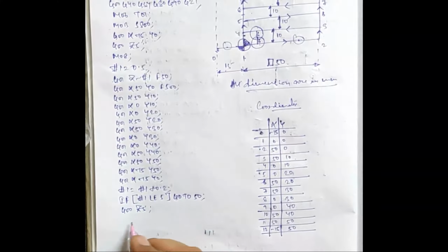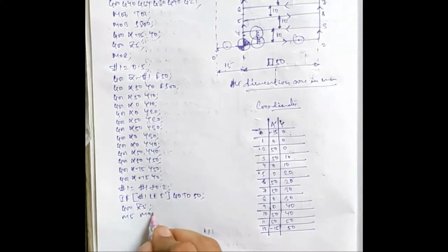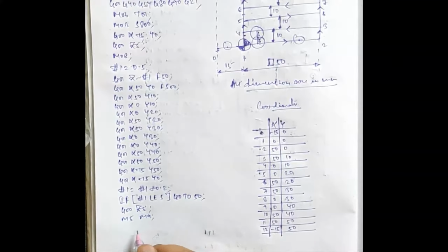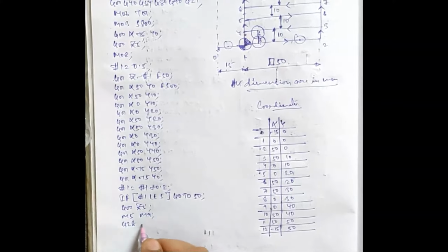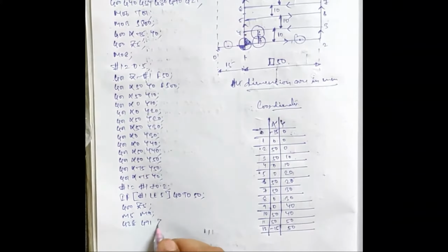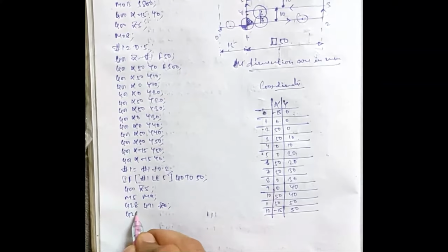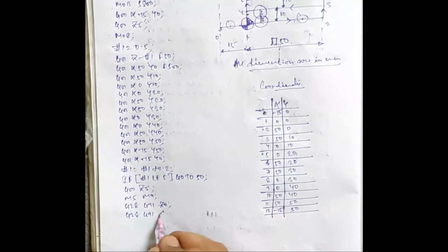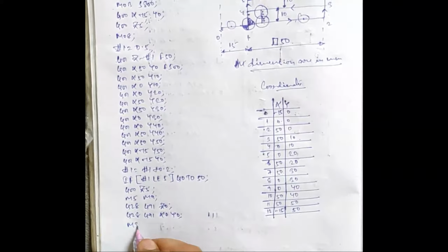Clear. Then M05 is your spindle off, M09 coolant off. Then homing, G28 G91 Z0. Then G28 G91 X0 Y0. Then your M30. Okay. Your program is not over yet.